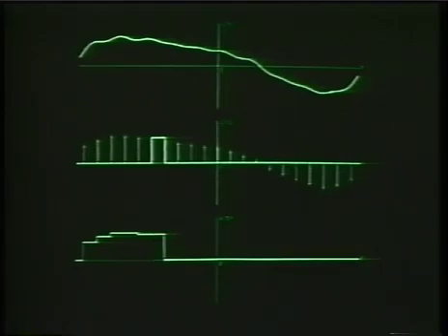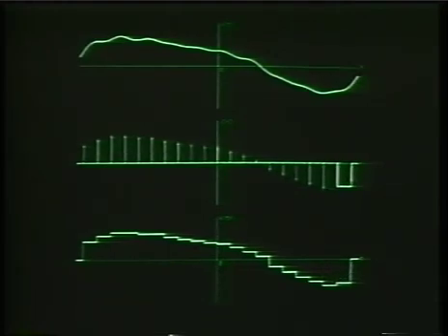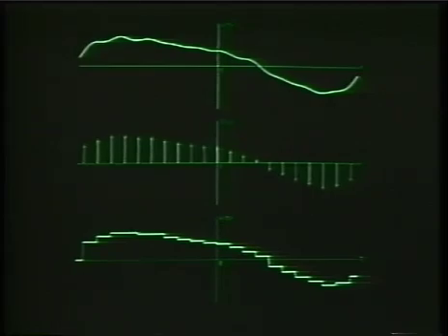And notice in this case, as in the previous case, that what we're basically watching dynamically is the convolution of the impulse train of samples with the impulse response of the interpolating filter, which in this particular case is just a rectangular pulse. And so this staircase approximation that we're generating is the zero order hold interpolation between the samples of the band-limited signal, which is at the top.